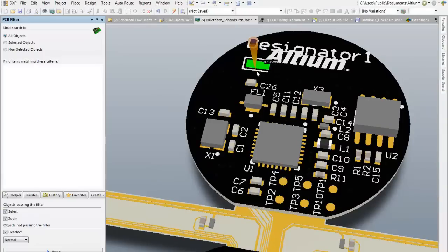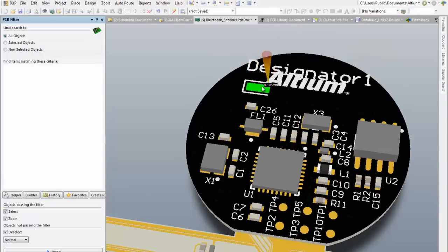Not only that, you'll want to make sure that height is right. Notice here it's showing me a violation. I am now intersecting with that top layer of the board, so my component height is larger than the area that is between the layers. So that is one of the things when you're defining that cavity: you want to ensure that height is appropriate. Otherwise, you'll see violations here. But this is an example of how it's recessed into the board.